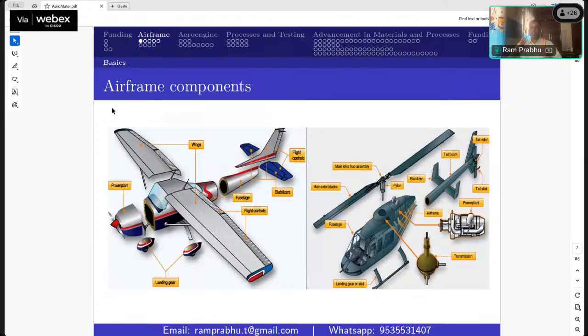But as a whole, 80 to 90% of them are made out of the same material, either lightweight alloy or carbon fiber reinforced plastic, except in the regions where EMI shielding or EMC compatibility is required, where glass fiber reinforced plastic is used.